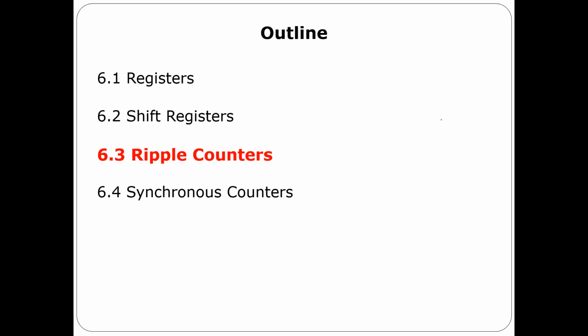So let's make a definition. The definition of a counter is, you have a hardware circuit. This hardware circuit should have a clock. For example, assuming here I'm gonna make a 3-bit counter. Again, guys, when I say 3-bit counter, it doesn't mean all counters have to be 3-bit. This is something I can design. I can make it 7 or 9 by just adding one flip-flop. That's it. Here I give just one example, and for others, I give one example for 4 bits, but that doesn't mean all others have to be 4 bits.